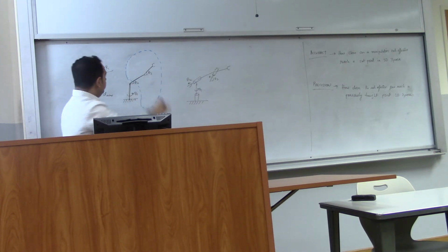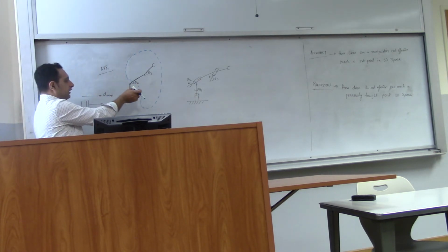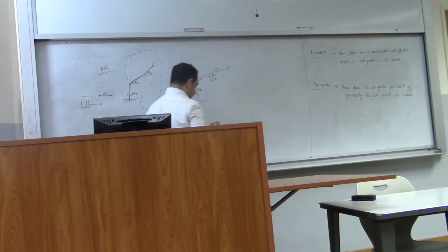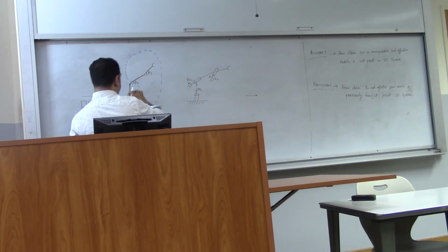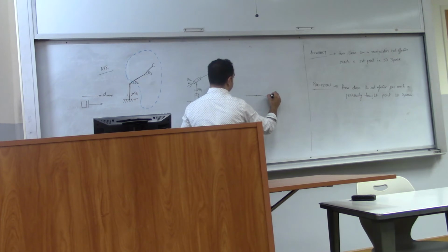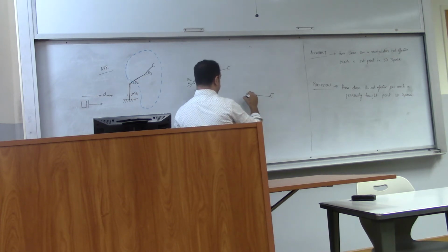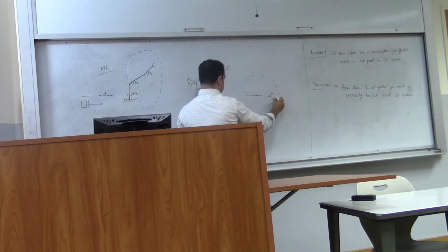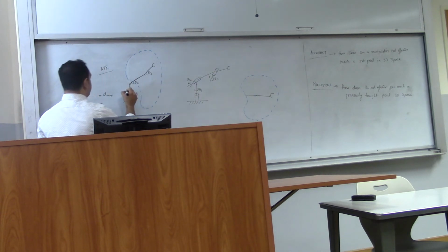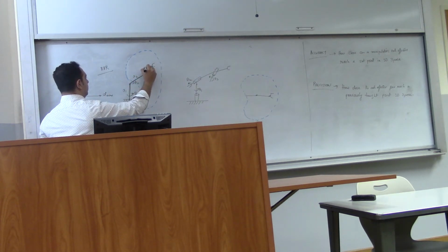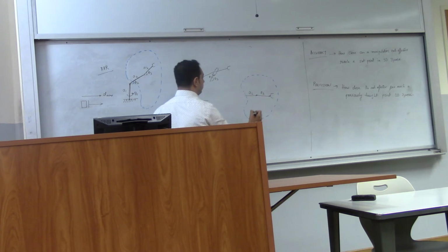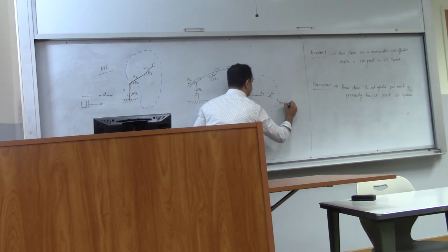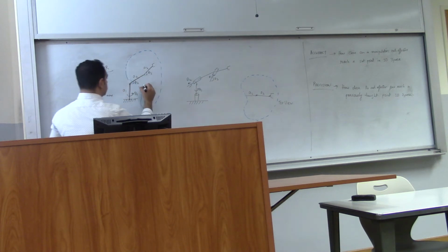Okay. The top view is when theta 1 rotates. From the top, you will see the manipulator like this. You will only see these two links from the top, because this will be a point projection. So if you call these links A1, A2, A3, this will be only A2 and A2 when you look from the top. This is your top view of the workspace. This is the side view.